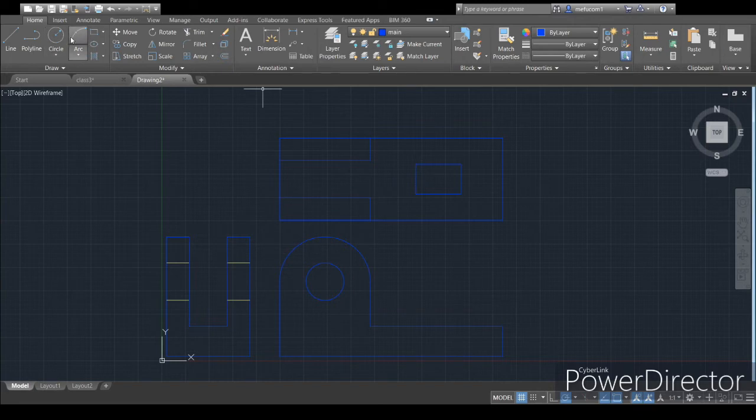You can either make an arc and go from here to here. And when you do arcs, let me go ahead and try this. Which arc do I want? Start, end, radius. Yeah, we'll try this. When you do it, I believe it says go counterclockwise. Start, end, radius. And we want that at 8. Bam.